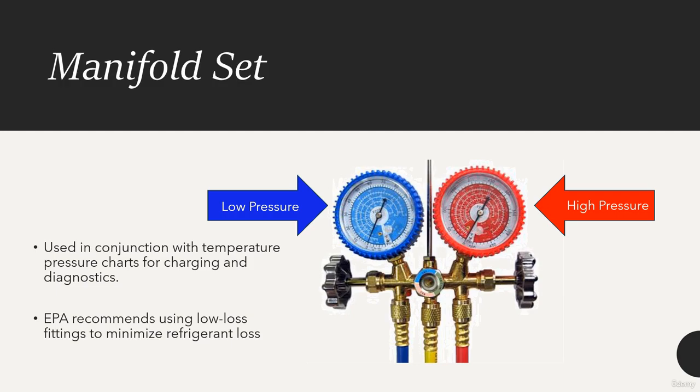Next, you compare the readings. When the system is operating normally, the difference between the high and low pressure readings is called the pressure differential, or pressure drop. The difference is an important indicator of the system's performance. Abnormal pressure differentials could indicate issues with the system.